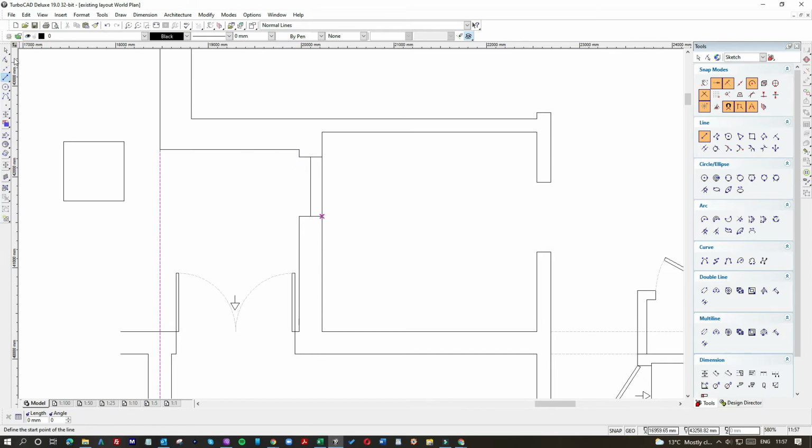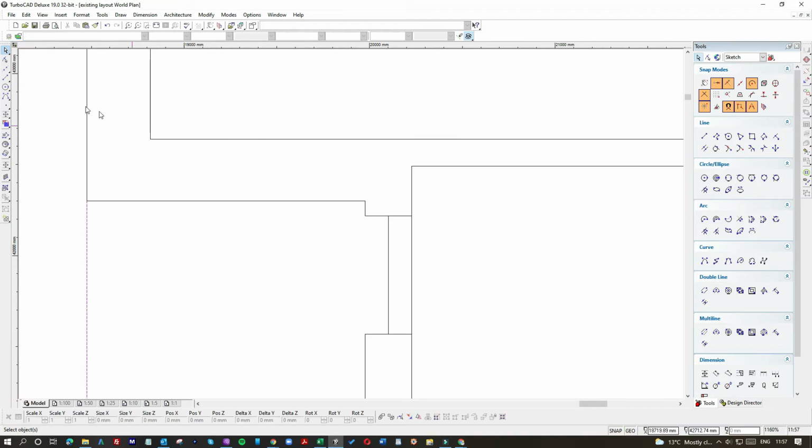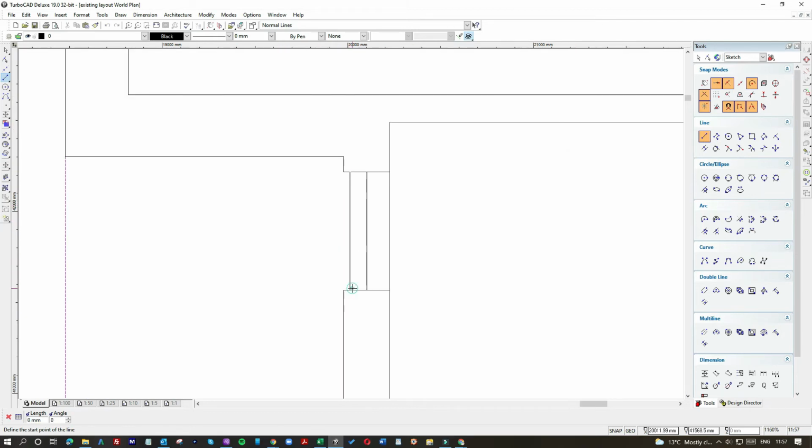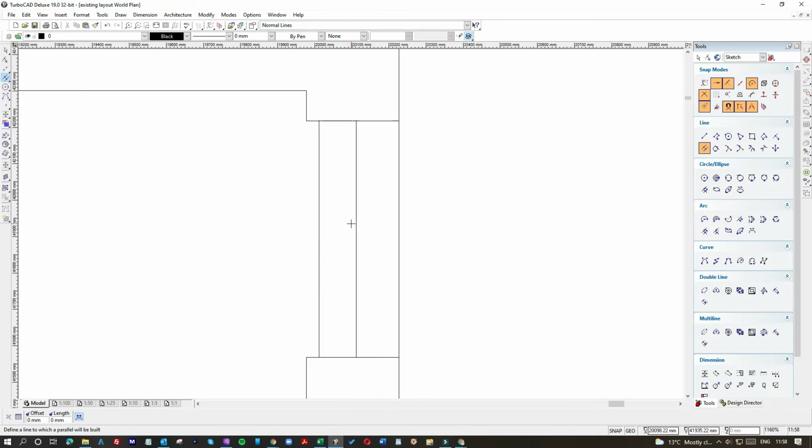So it's always difficult. But generally speaking, on modern double glazed windows, we set those approximately 35 mil back, which means that this center thing doesn't work. So let me just do a double line here, double line, and we go tab -100.